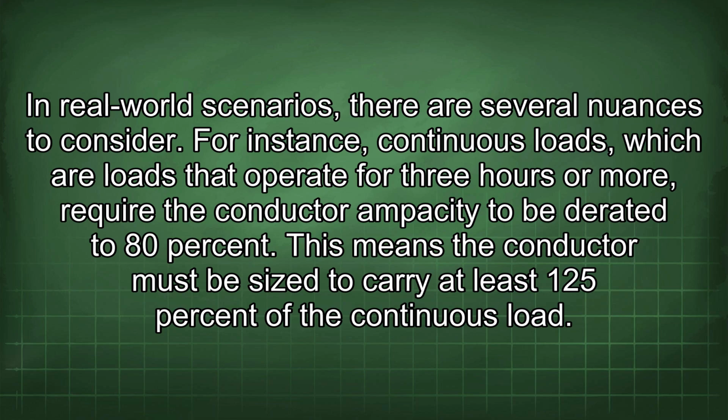In real-world scenarios, there are several nuances to consider. For instance, continuous loads, which are loads that operate for 3 hours or more, require the conductor ampacity to be derated to 80%. This means the conductor must be sized to carry at least 125% of the continuous load.